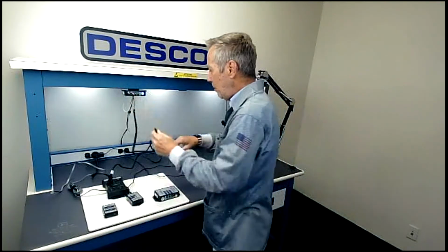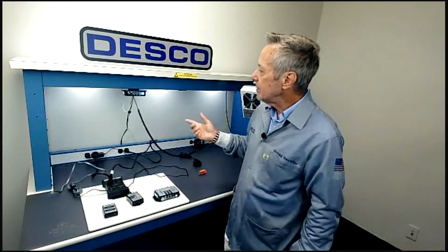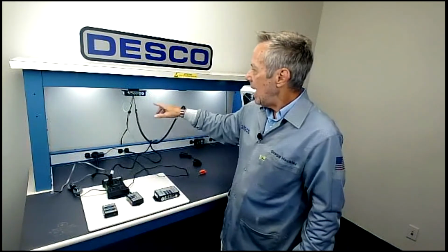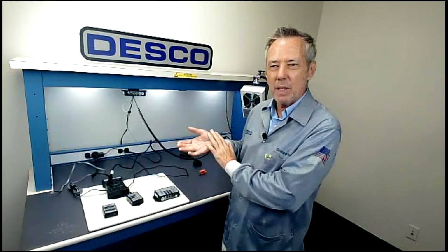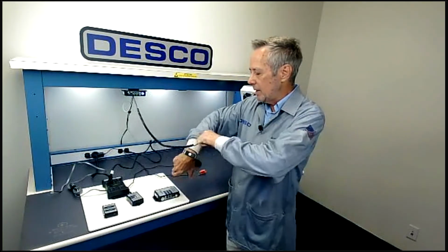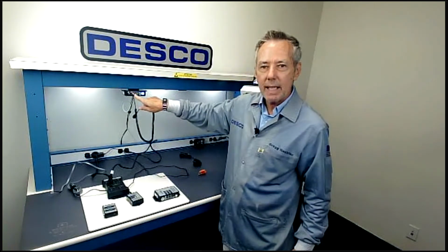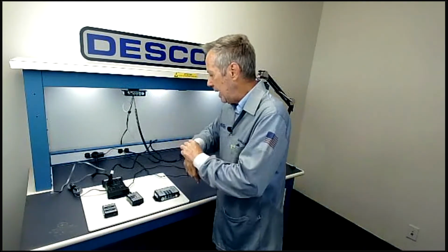So I'm going to put my wrist strap on right now. Under a normal state, you can see all these green LEDs, and I also have this continuously lit blue LED right here. So everything's wonderful with the monitor. My body is under the specific amount of required resistance, impedance, and we're ready to go. If I were to have a fault, as with any of these monitors, I now get that audible alarm. I'm also getting a red LED, which may be hard for you to see on the camera, on my monitor. That would happen with any monitor.